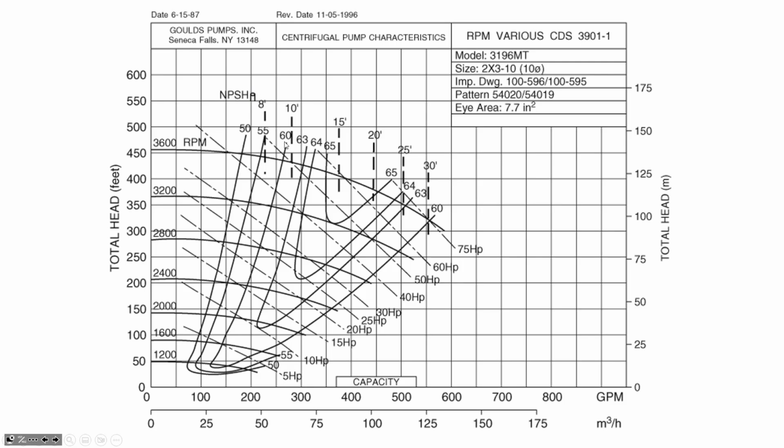It's the amount of suction head that is required by a pump to prevent cavitation. And so that's something that every pump is going to be slightly different. You can get the information from the pump manufacturer and then do the calculation if cavitation is at risk. Any questions about this figure before we move on and talk more about cavitation risk?